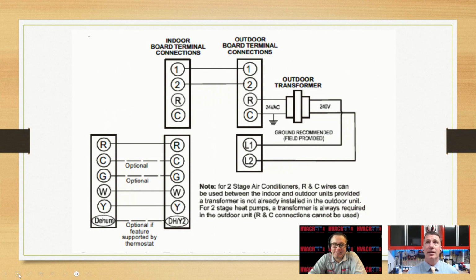That is actually how we have our common reference from a ground of the outdoor unit, or common in the outdoor unit, back to the panel, back to the common of the indoor unit. The panel is our loop service. So if I had a furnace that was tied onto an old 2-wire system coming from a plug in a basement, and I put a new communicating system in it and it doesn't communicate, guess where my problem's at? Got a bad ground, or in this case, a bad reference. Exactly. That is exactly right.